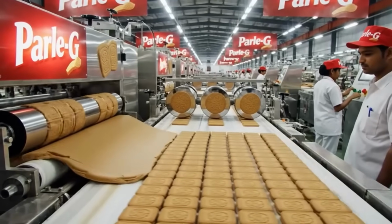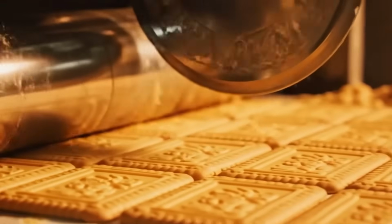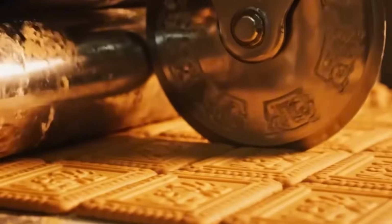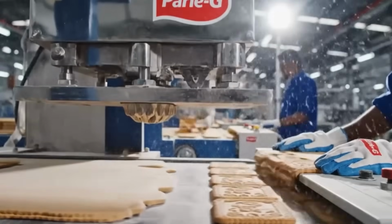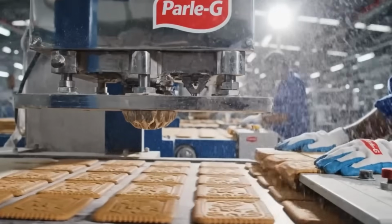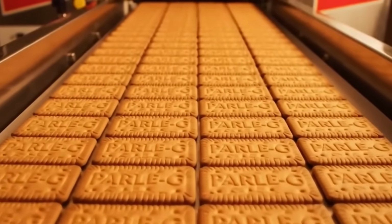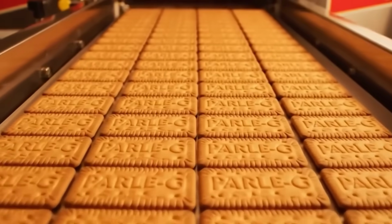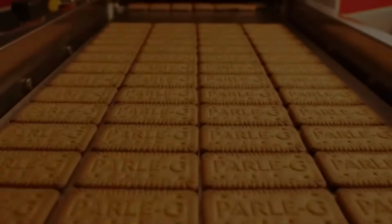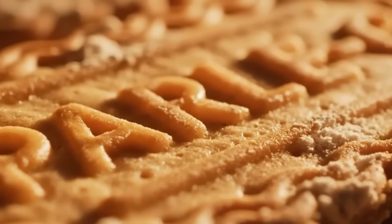Moisture endpoint is a primary target because it defines crispness and shelf stability. For crisp biscuits, the line drives moisture low so the biscuit fractures cleanly. For softer biscuits, the line stops earlier to retain more moisture. Moisture control is managed by oven profile and by piece thickness. A thicker biscuit needs longer bake or higher heat. A thinner biscuit can overbrown quickly if heat is too high.